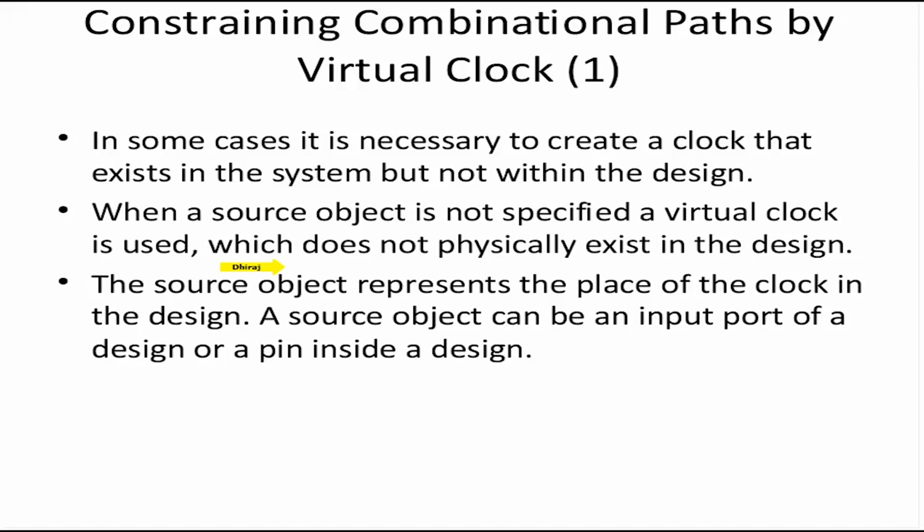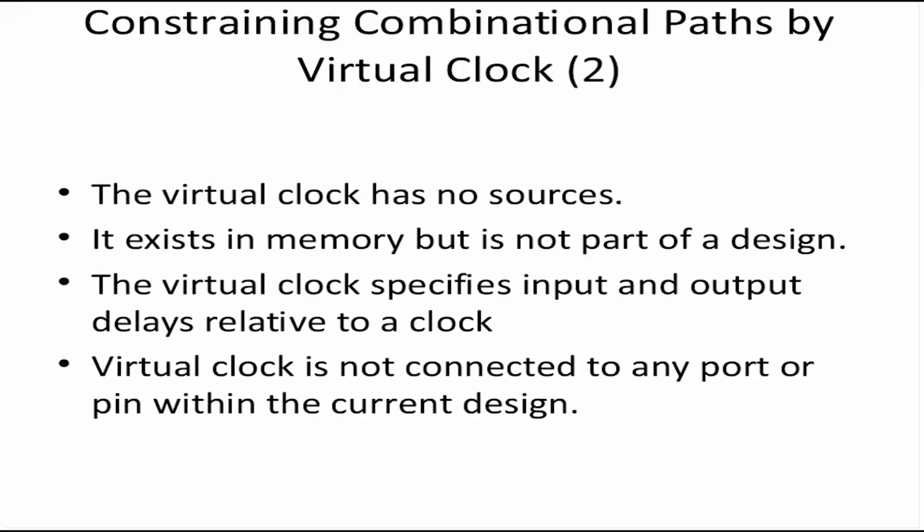The source object represents the place of the clock in the design. A source object can be an input port or a pin inside the design. So whenever you create a clock, in most cases you need to specify whether you are creating a clock at the input port or a pin inside the design. If this source is missing, then the clock is called a virtual clock. A virtual clock obviously has no sources. It exists in the memory, but it is not part of the design.